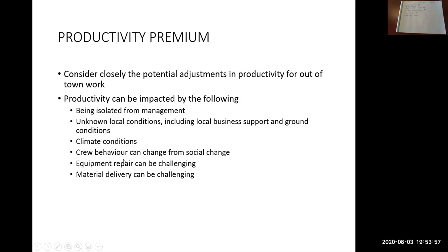Maybe in the lower mainland, you think you can place 50 cubic meters an hour of road base with your little dozer. But if you can't get it to the job site that quickly, then maybe you're down to 10 cubic meters an hour, simply because the material can't get to the job site quick enough. So those are things that you could ask, for example, the gravel supplier. You can ask them, how many trucks a day can you get me to the site of the different materials that you need? And it's really going to vary depending on the specific gravel supplier that you're talking to.